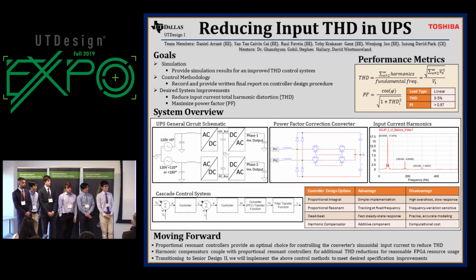Number one, does yours do an AC to DC conversion all the time? Yes, it is a double conversion system. So it always converts from the mains AC to DC and then DC to AC. Well, good. So that means it probably sacrificed the front end in a lightning strike, but it might save the rest. But anyway, any UPS system needs some good lightning protection in the front end. Toshiba hasn't really explained any of that to us, so I can't really comment on that, but I understand.